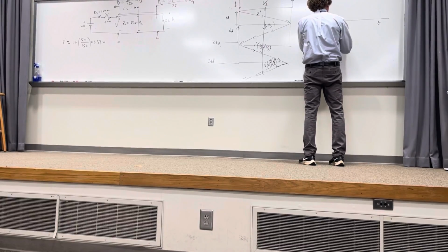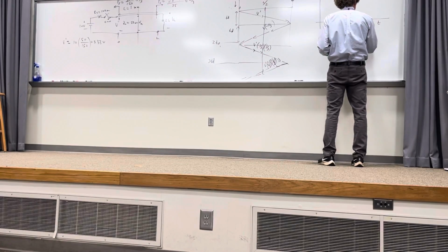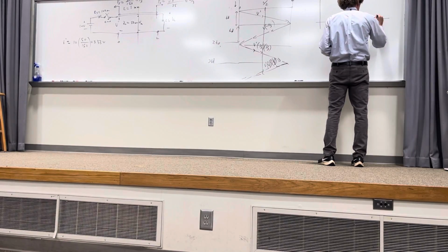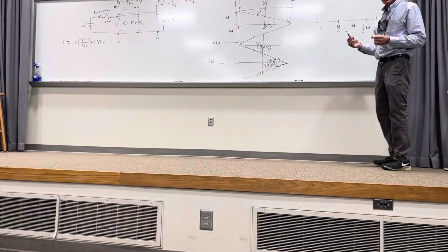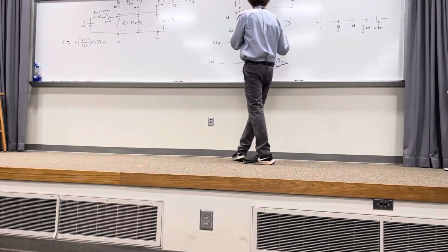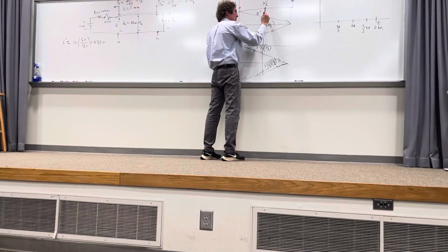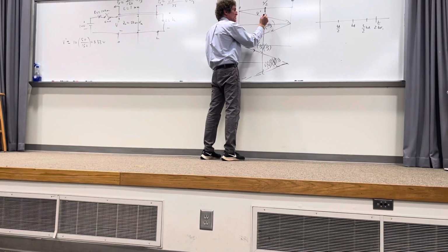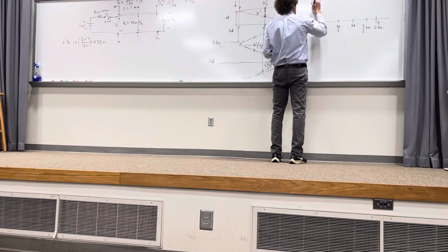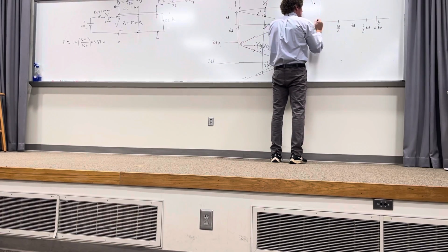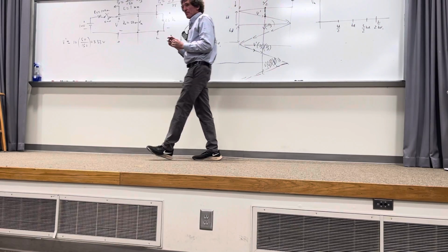here I'm going to put TD over 2, this would be TD, this would be 3/2 TD, and this would be 2 TD. The reason I'm doing 1/2 TD is because if I trace this line, I start right here, as I'm tracing down, nothing at all is on that until I hit this point. So this would be the voltage at the midpoint. It would be 0 until I hit here. You all agree with that?